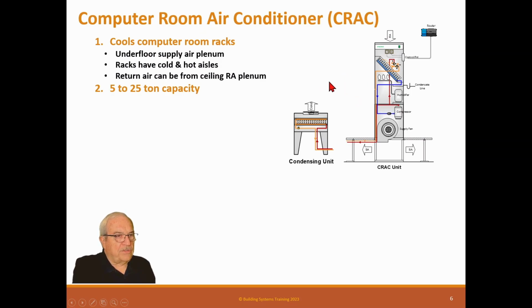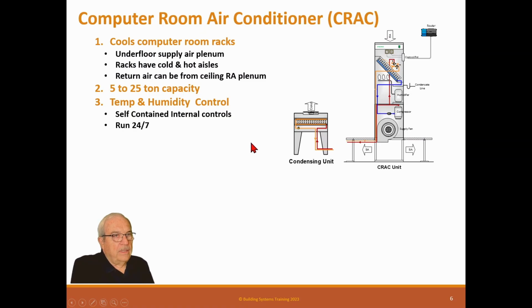They go above the ceiling and basically blow the condenser air into your space, which we don't use unless you really have just some little spot you have to do. But what we do is we do a whole bunch of these. So if you have 100 racks inside your computer room full of servers, we will put probably 30 or 40 of these around the space in line with those racks to provide cooling under the floor for these racks.